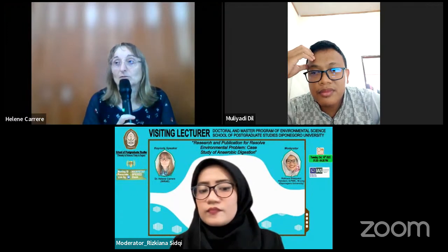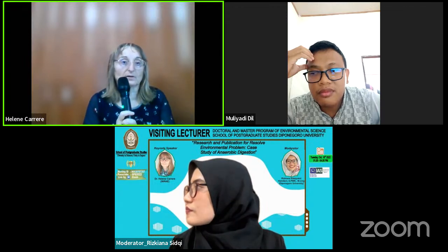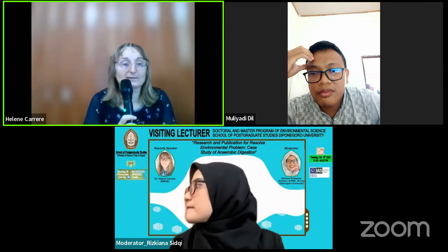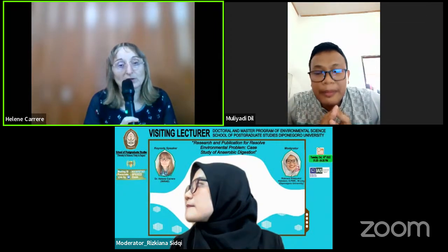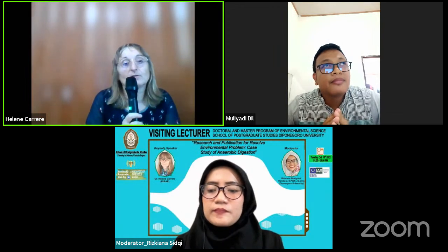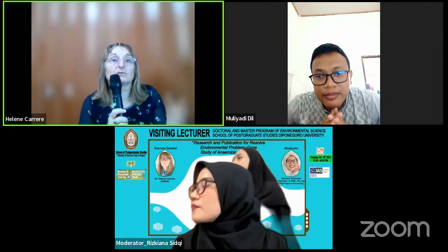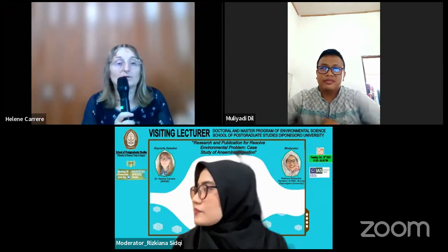So that's the first method. Another method is to work also in acid conditions. The methanogens need a neutral pH, so in acid conditions you will not have them. And also to work with a low retention time, lower than the growth of the methanogens. So with less time in fermentation, still we are speaking of dark fermentation. Usually it's a few hours for wastewater, or it could be up to 2 or 3 days for solid waste.